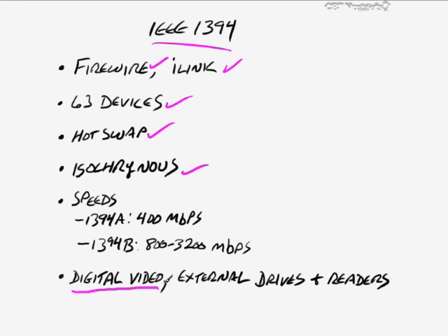You'll find that your digital video data stream will normally transmit from the camera to your computer, for example, more reliably if you use a FireWire connection than if you use a USB connection. And that's part of that is just experience on my own part. But even though cameras will very often have both of those kinds of connectors, I think you'll find that you'll get a better result out of IEEE 1394 or FireWire. By the way, that's the Apple name, and the Sony name is iLink.